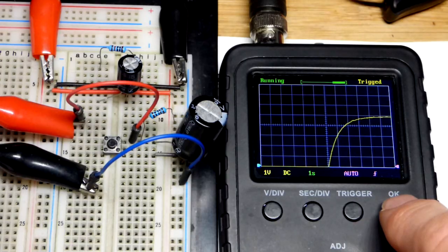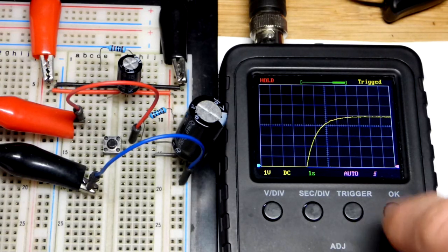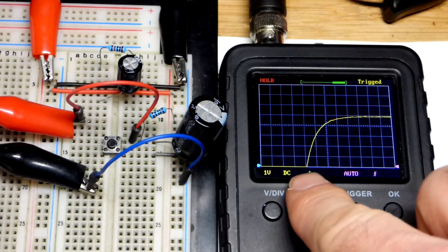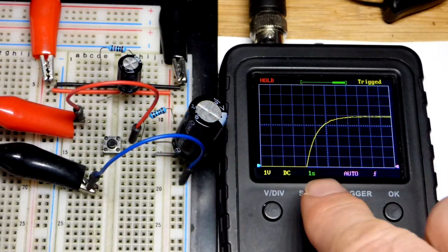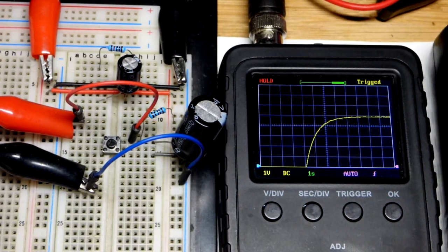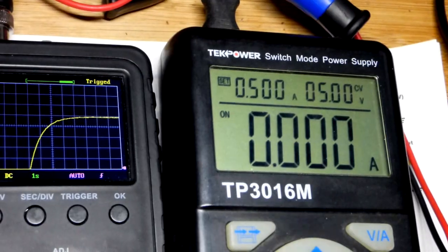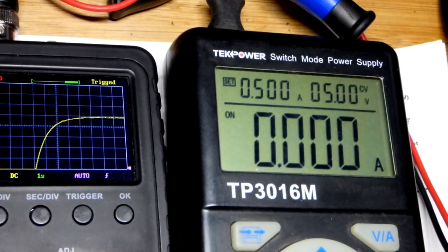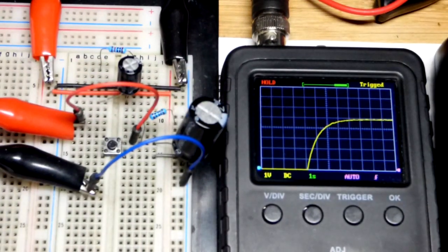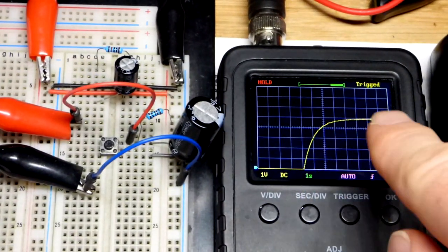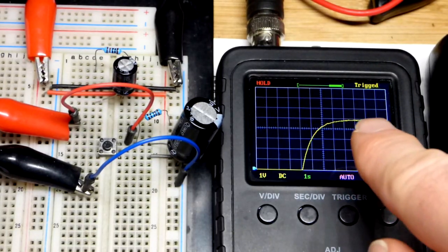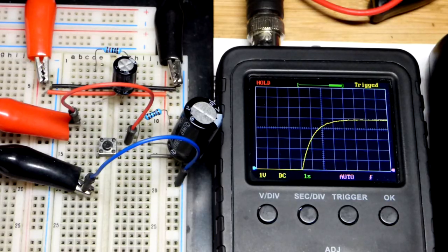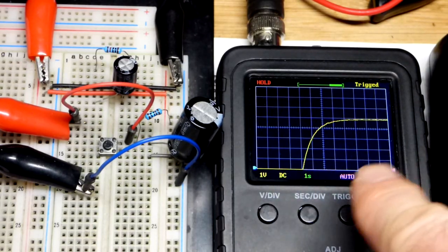And I'm going to try to stop so that we're at one of the divisions right at the beginning there. I don't think I landed it perfectly, but it doesn't really matter. Due to the value of these two components, we're working with 5 volts at the power supply right there. So that's what it charges up to, 5 volts. We have the curve that you see here. So we got 1, 2, 3, 4, 5. That's about when it becomes fully charged right there, after about 5 seconds.